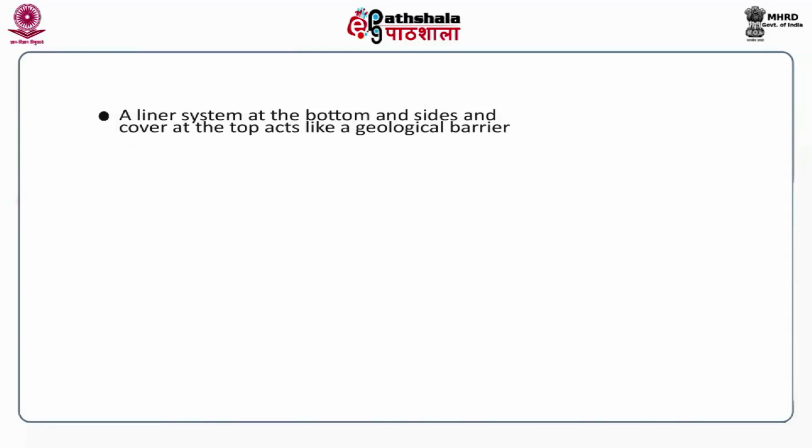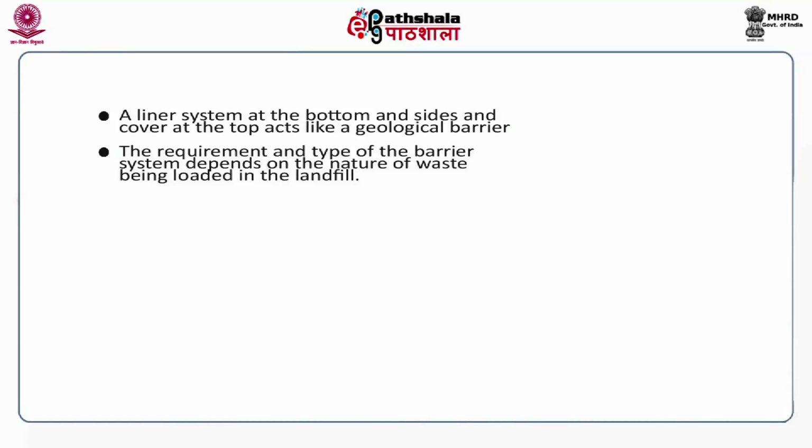Now, a liner system is provided at the bottom, the sides and on the cover, acting like a geological barrier. The requirement and type of the barrier system will depend upon the nature of waste that is being loaded. Both natural as well as synthetic materials are used as liner barriers.